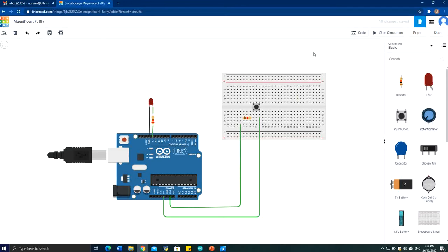The next step is that you need to select which GPIO pin will be used as an input. So let's say in this case just select pin number D10. We select that as an input. So for pin number D10, we need to connect it to this part. So based on this connection, if the button is not pressed, this pin will be connected to the ground. So for this case, the value will be 0.